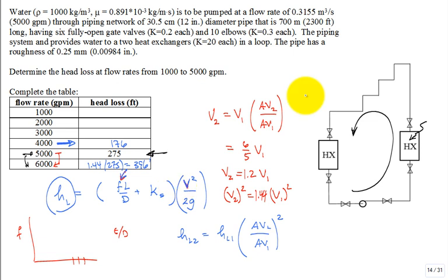So if you wanted to plot the curve for the head loss as a function of the volumetric flow rate for a closed system. What do you mean by closed system? It's not putting it to a higher elevation tank. It's not lifting it, and it's going in a loop. That loop may go to the top of the building, but then it's back down to the bottom of the building. So the elevation change cancels out because you're going up in a pipe somewhere and you're coming down in the pipe somewhere. Okay? Open system is different than a closed system, but this is a closed system.